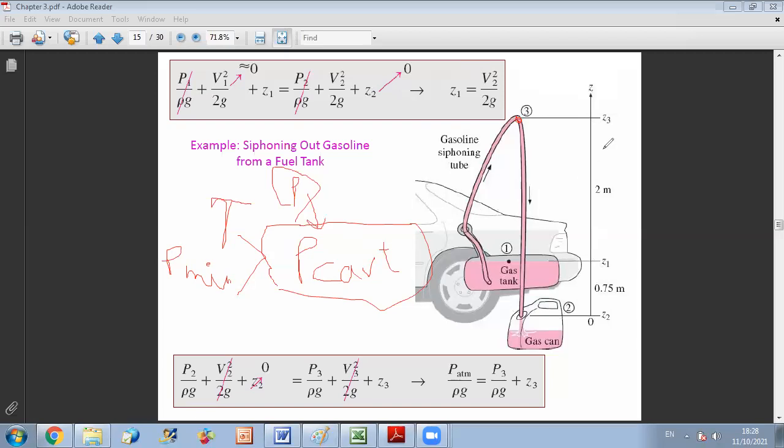Why will point 3 correspond to the minimal pressure? Because as you move up from this point, what is happening? If you apply the Bernoulli equation, you have the same cross section in the tube, and by conservation of mass the flow rate is constant through your tube.